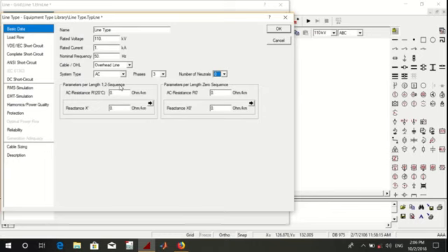Then go define the parameters of length, positive and negative sequence, and zero sequence of a transmission line. Here I give approximate values, my desired values, but in a real project you should give the real values of the positive and negative sequence resistance and impedance of the transmission line. But the point here is that in a transmission line, we know that the zero sequence component is twice or greater than twice the positive and negative sequence impedances. Here I gave a resistance of 1.45, like any value you give, and 0.674. Here the resistance, if you want to give approximate values, or your arbitrary value, it should be at least twice. Twice of 1.42 something it becomes.